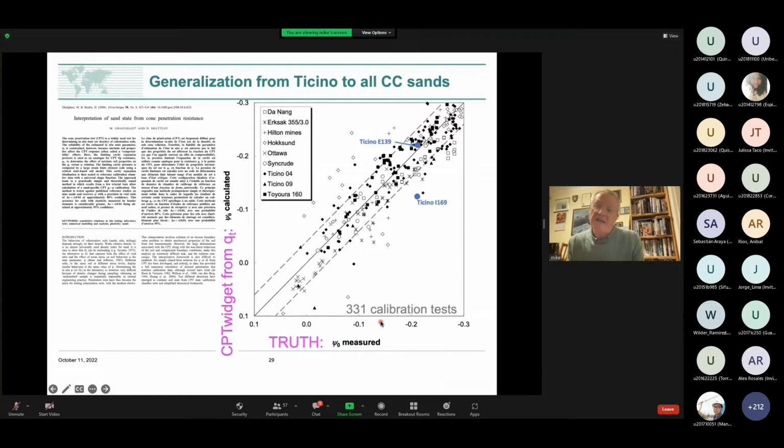They've then done this test and they've reported a QT value for that e, p0 pair. So we've said, okay, for that particular sand, we know what its properties are. We will take it through this finite element procedure I showed you, calculate out the K and M values, and then from their reported QT, we can calculate out what the apparent state parameter is. And that is the cross plot. The line down the middle is the one-to-one equivalence line. And see if I've got the numbers on it. Yeah, 80% of the data lies plus or minus 0.04 of the calculation.